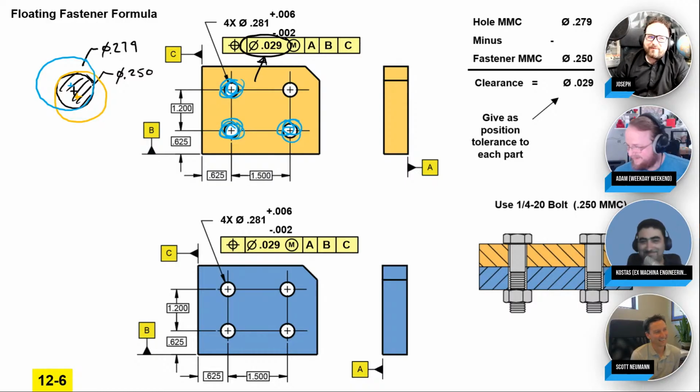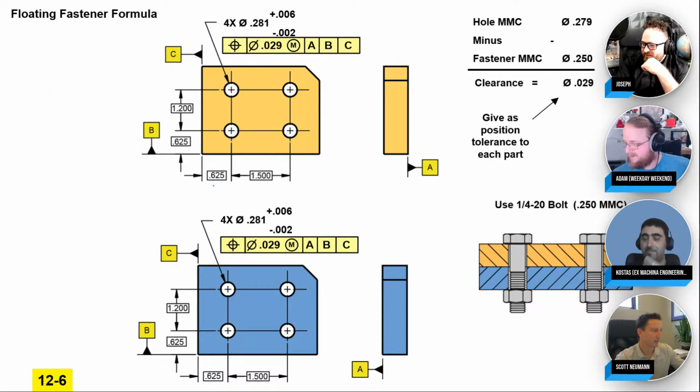If I remember my numbers right, this gives you 56% more tolerance than if you were using plus minus dimensions, right? That's right. Plus minus, that's a nightmare system. You have to put plus minus on instead of position tolerance. That's what we used to do in the 1800s and early 1900s. We used to put plus minus on the dimension, on every single one.